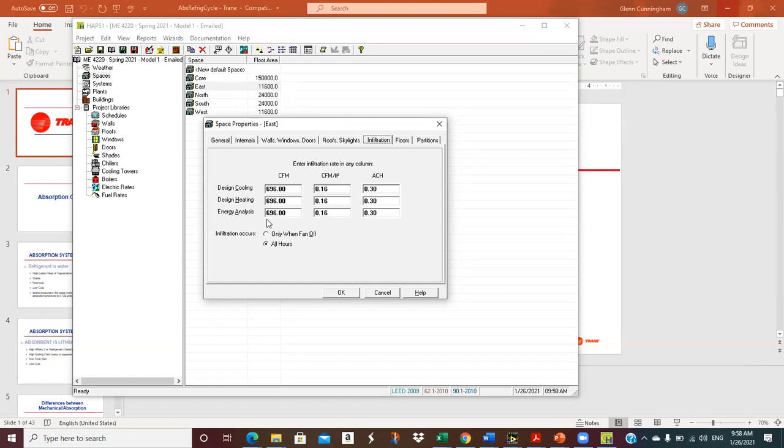So I typically put in the air change number. If you look in the HVAC or in the ASHRAE literature, there is what they call a crack method. And oh my goodness, you can look up typical indoor-outdoor pressure differences. You can look at cracks. You can measure or calculate the crack length all the way around every window on the face of the building.